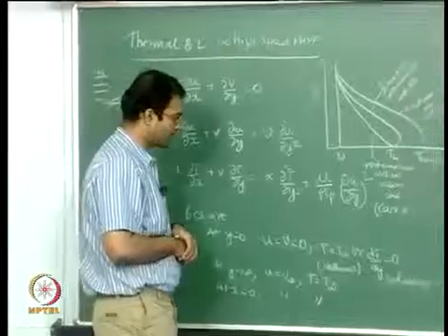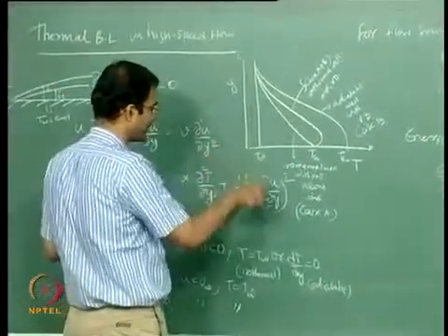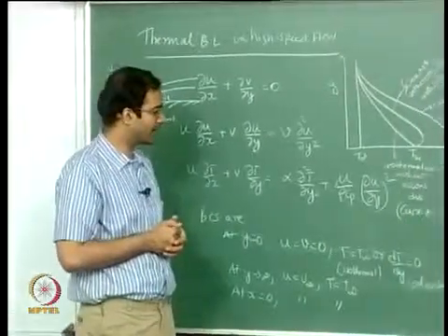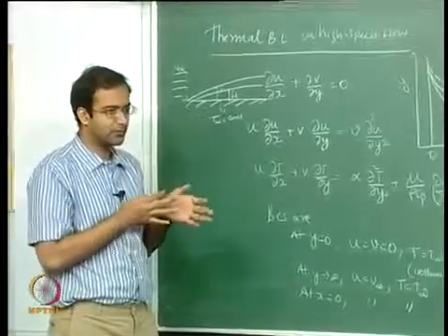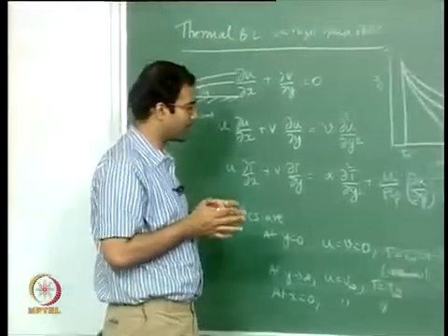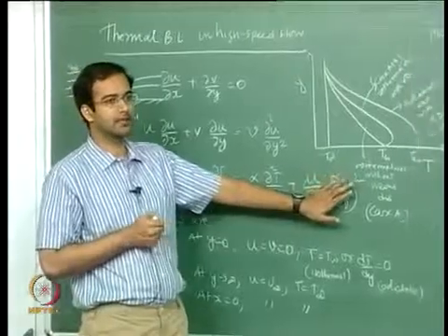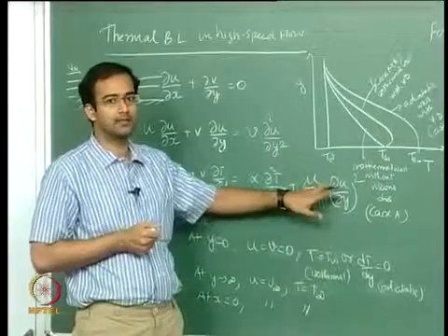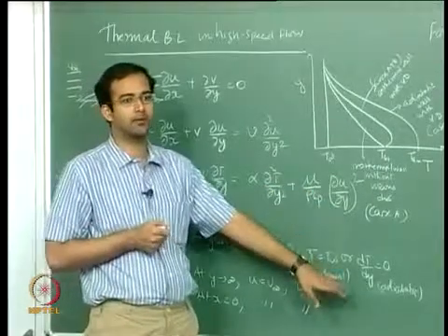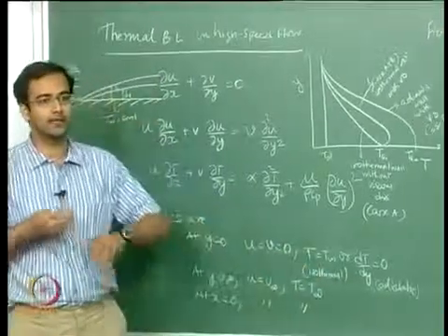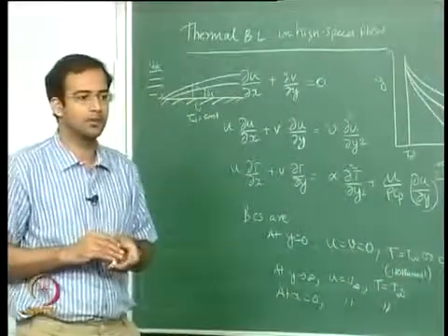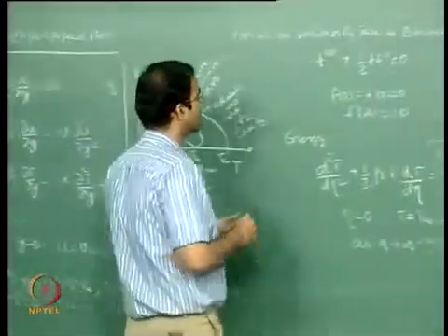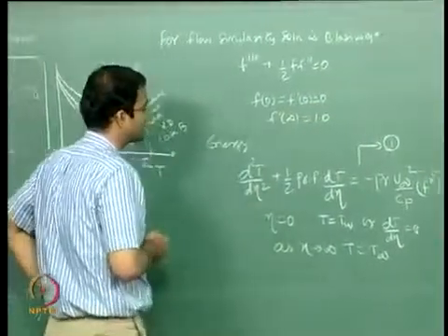You can consider this problem as two sub problems. Since the energy equation is quasi linear, you can split this into two sub problems with two different boundary conditions. One problem is where you don't take the viscous dissipation term into account and you assume a purely isothermal wall. In the other, you take the viscous dissipation into account and you maintain an adiabatic wall. So even with an adiabatic boundary condition, you have heat transfer possible because of the viscous dissipation. Of course the similarity solution for the flow is still the Blasius solution.